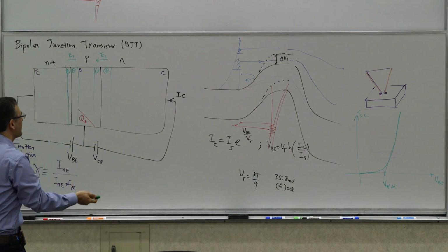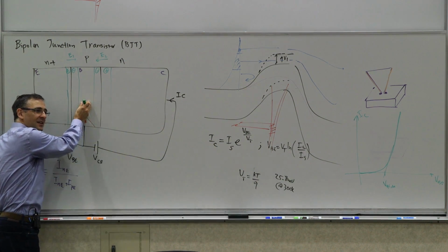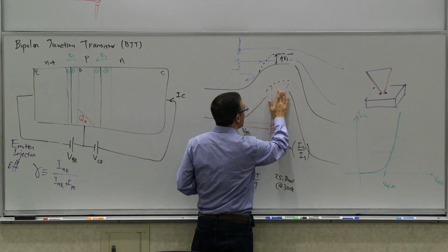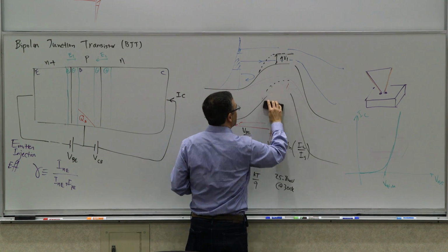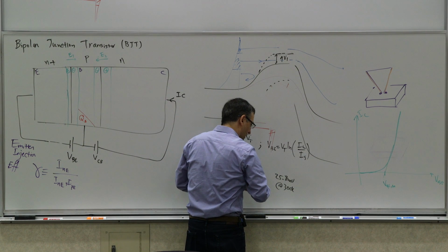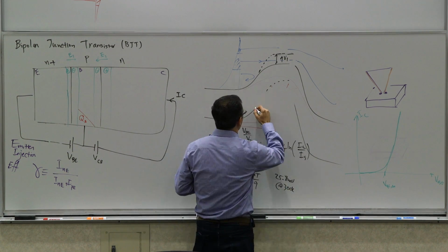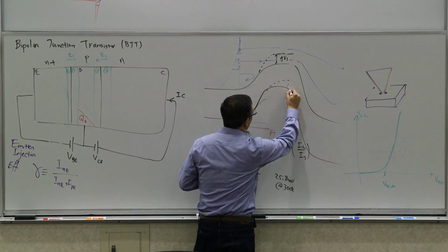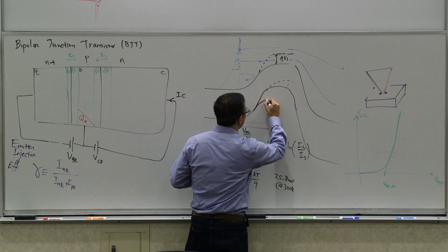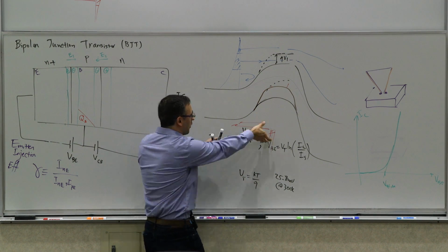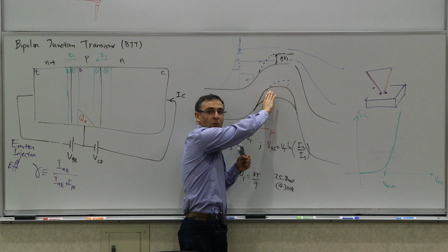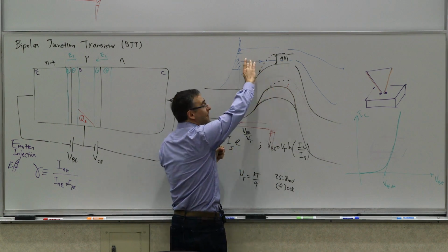So use a slightly different semiconductor material in the base. A slightly different semiconductor material will have a different band gap. And if it has a different band gap, you can make it so that it will be, let me use a color I haven't used, instead of where it was, now if it has a narrower band gap, let's say here. So instead of this, you will get that. So this whole thing gets shifted up, which means that you have a larger potential barrier in one direction for the holes than you have for the electrons.